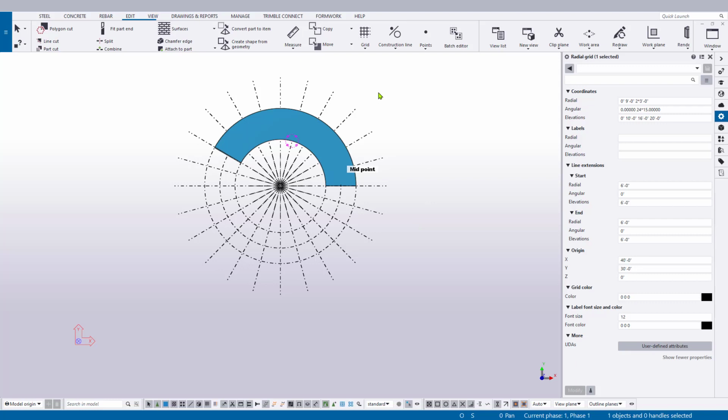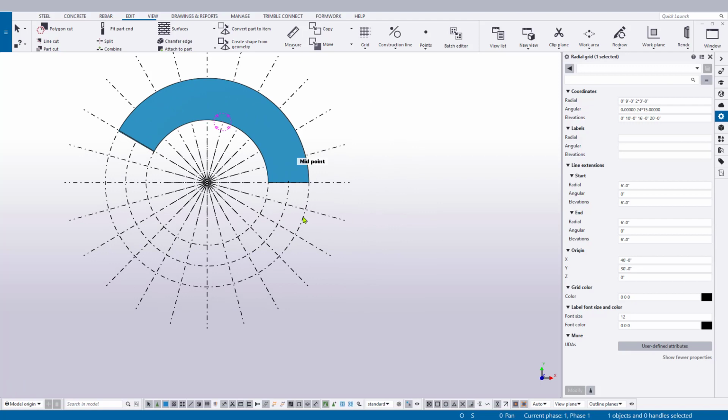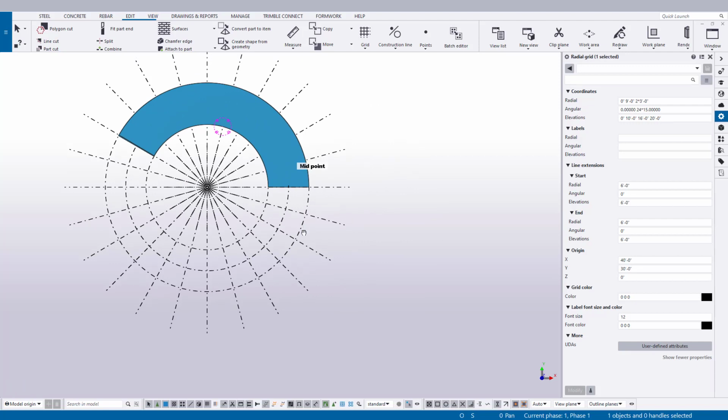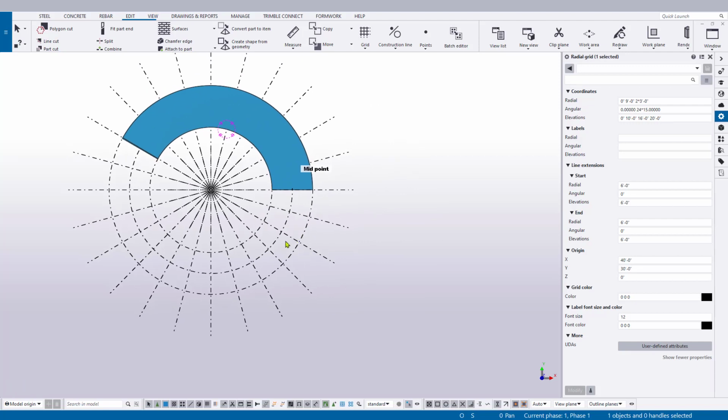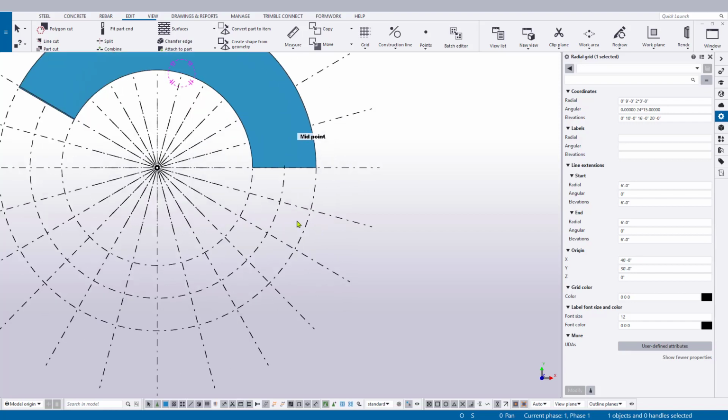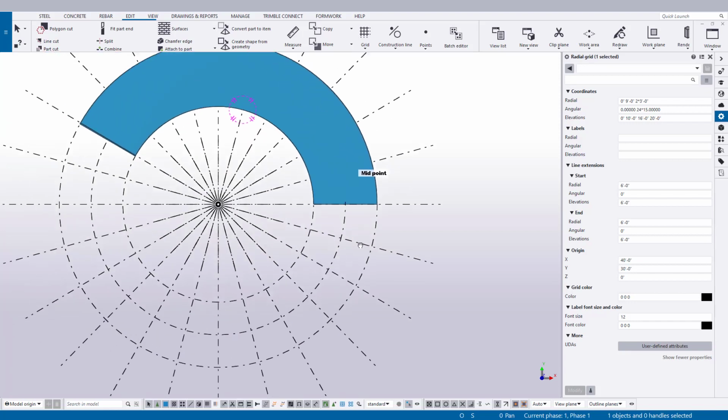This is a really quick way for me to have a lot of clicking points around a center axis, and you may want to consider putting in a radial grid before really working with your concrete or rebar for these types of structures or any round structure. You can always delete it later if it's not part of the project, or if you have one, I would suggest starting with those parameters first for a radial grid that's on your documentation before proceeding.